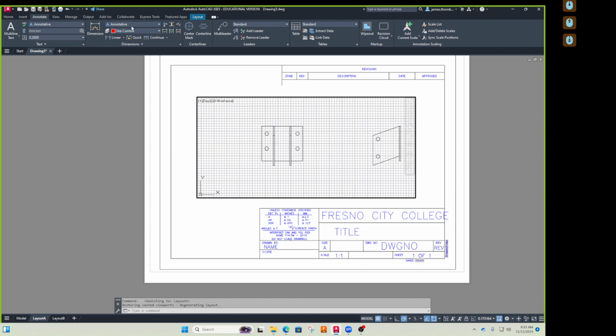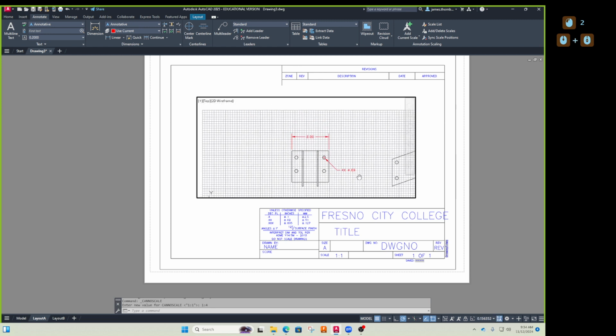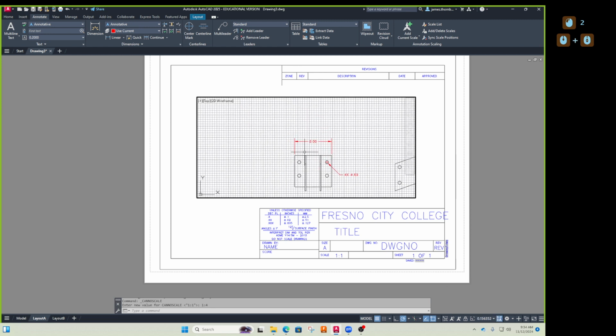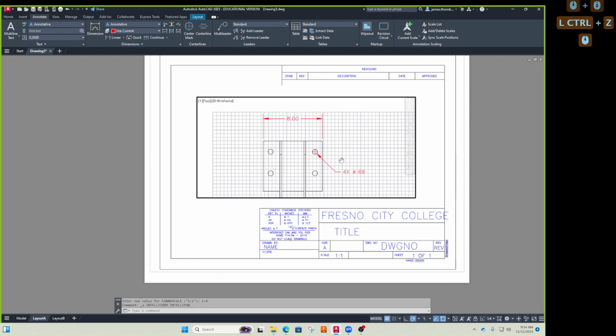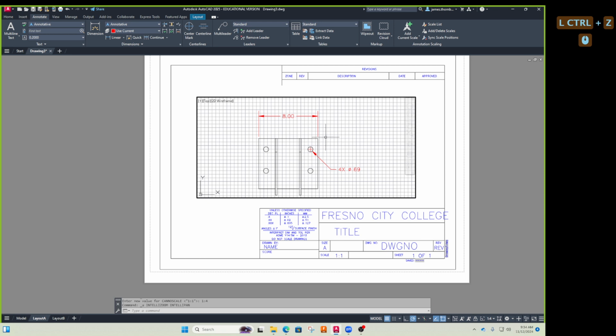So we're using annotative dimensions, right? So what is it linking? What is it kind of connecting to make sure it's the right size? The scale factor, right? So if I go to that 1:4 scale factor, boom, there it is. Even if I then change it on accident. So it's meant to show only at that scale factor. It's only at that scale factor it shows, right?